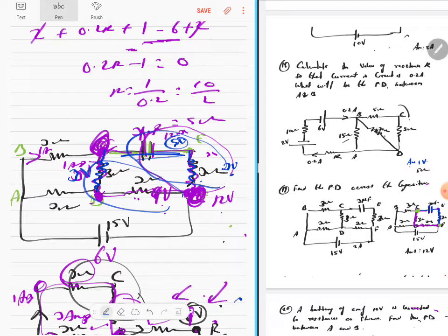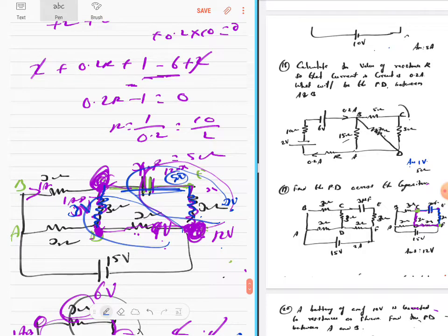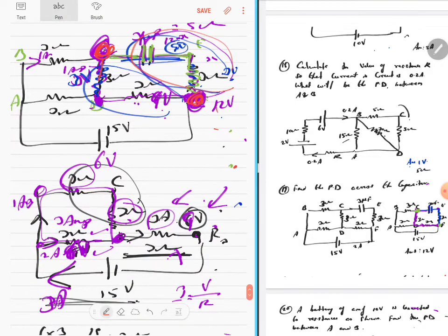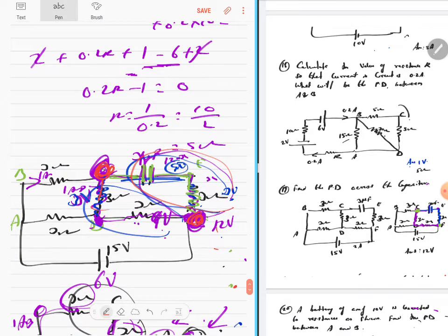It's such a complex sum, it's not a very easy sum. First thing is you should identify how to get the potential across the capacitor in this circuit. You should take this off separately from here to here, because that potential and this potential are just the same. Take this circuit off, redraw it without it, mark the currents, then find the potential difference to be this plus this potential, which is 12 volts.